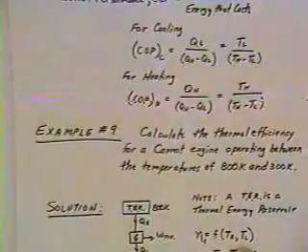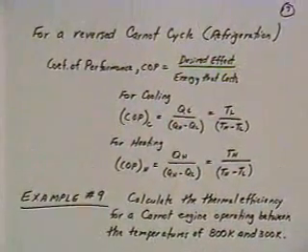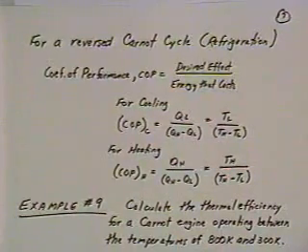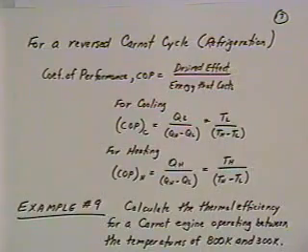And so these are some of the things for power cycles, either for a Carnot cycle or for the Rankine cycle. And now we'd like to take a look at a reversed Carnot cycle for refrigeration, and again talk about the terms here, and we're now on page 17. For the reverse Carnot cycle, which is the refrigeration cycle, it doesn't make sense to talk so much about efficiencies, because for a refrigeration cycle you're not interested in how efficient the cycle works. You're really interested in heating or cooling, depending on whether your cycle is a refrigerator or a heat pump.